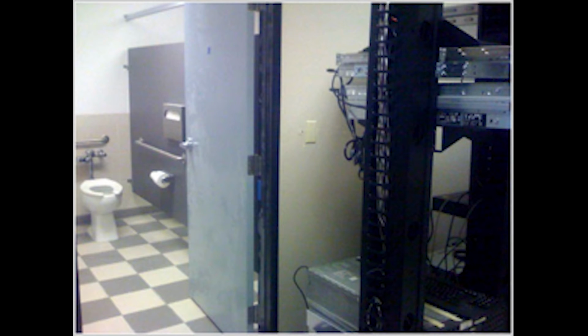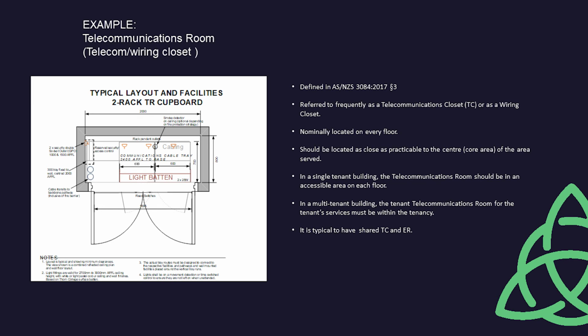As stated earlier, the rooms must be above the forecasted flood water level for the life of the facility. If this is unknown, or there is doubt, use the 100-year flood levels. This should accommodate for climate change. This changing environmental situation that we find ourselves in must be included into our design considerations. It is a fair and reasonable design criterion to nominally assess that there is approximately a 63% chance of one or more of a 100-year flood events happening within the life of the building.